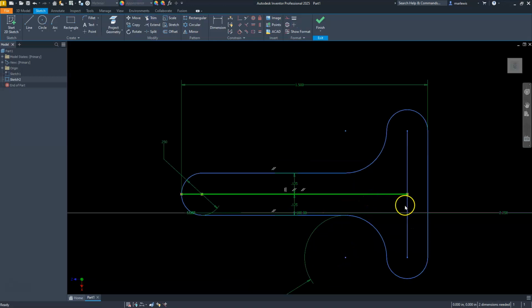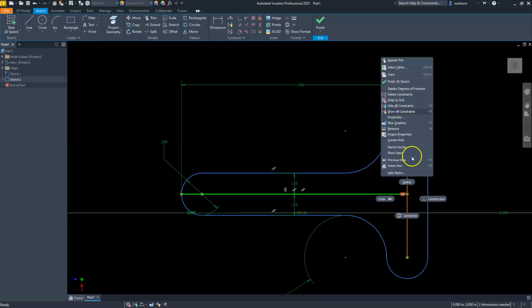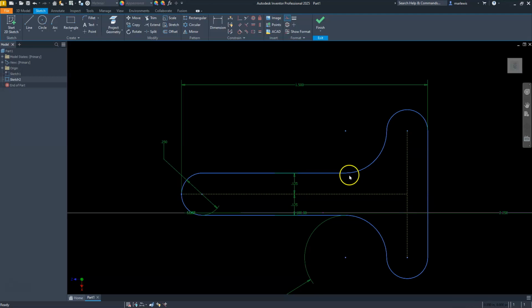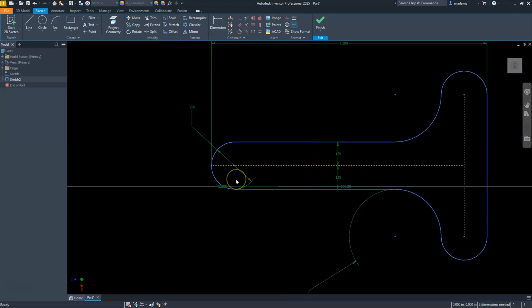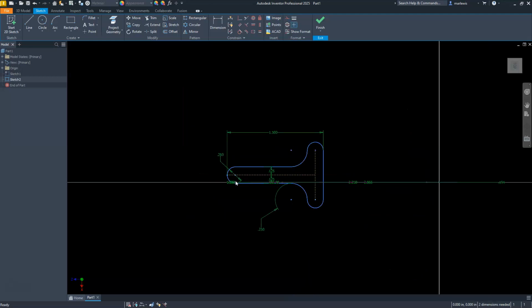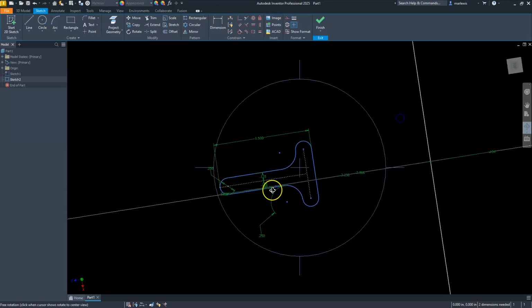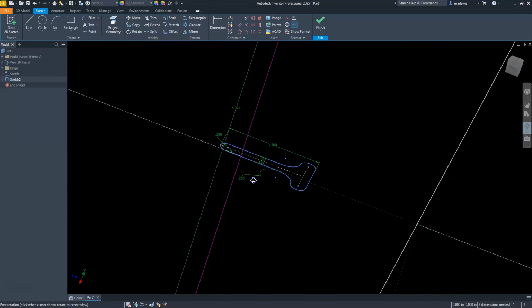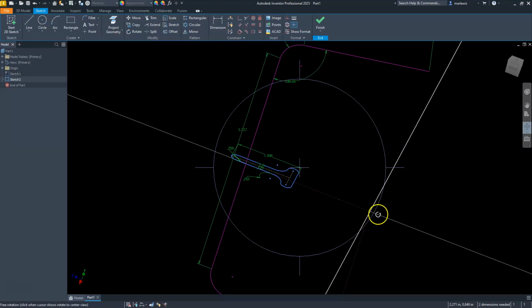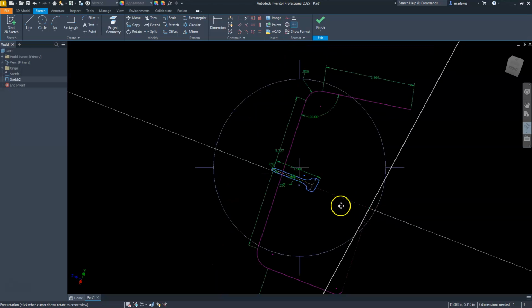And then I'll go ahead and select both of these. Remember, you have to hold down the shift button to select both of them. And I think we have everything that we need. Let's see. It's almost fully constrained. Let me rotate this thing sideways because it's looking for where this point is with respect to this axis here, or this point here.